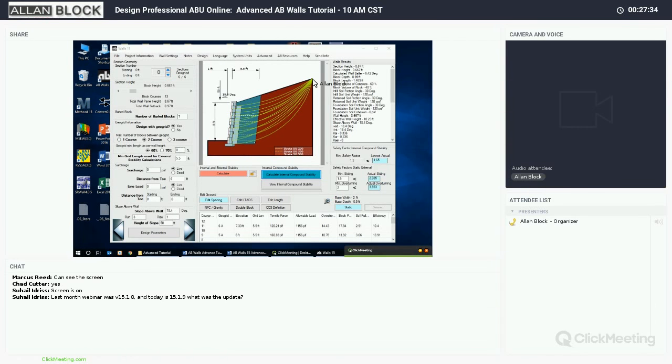And then if you really change it up, let's go to the design parameters here. If I use 27-degree soil, which is more of that clay material, and let's face it, we work with a lot of clays. So if I hit hide here and now I hit calculate, instead of 6, you really jump your grid lengths.